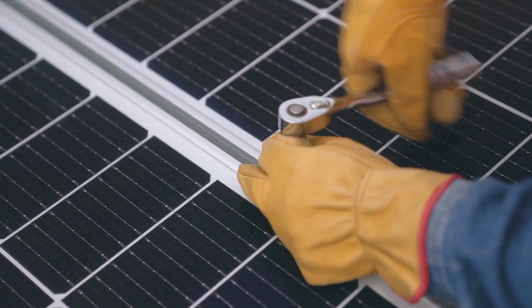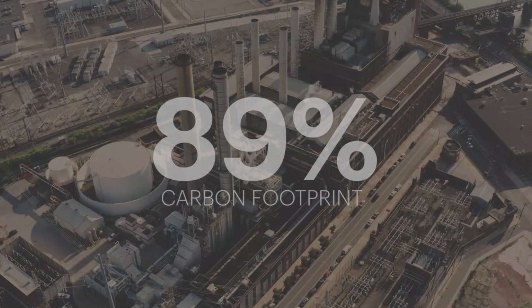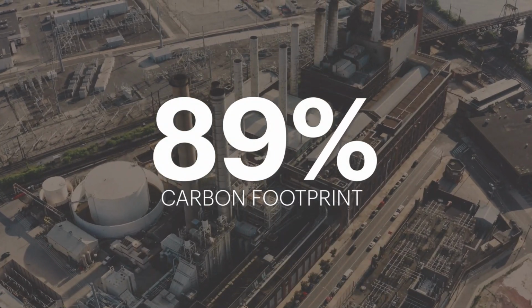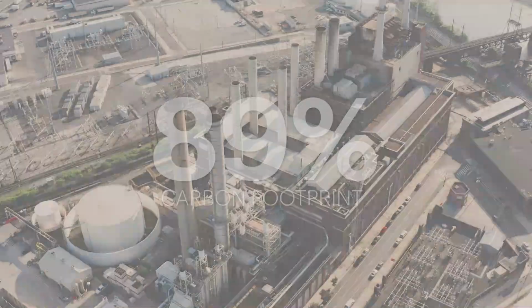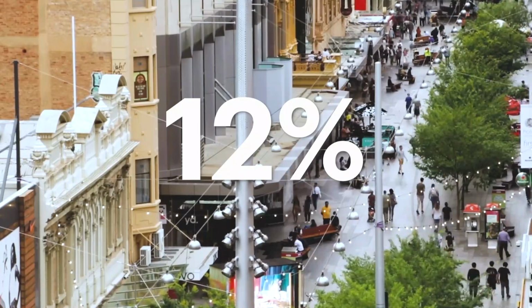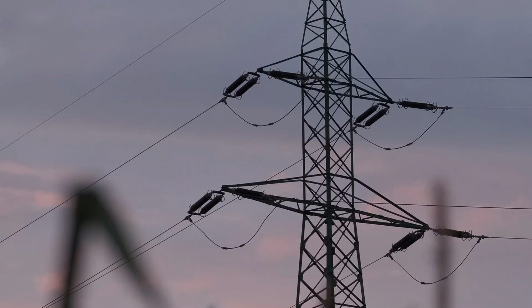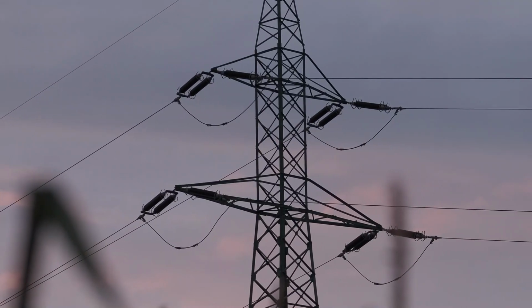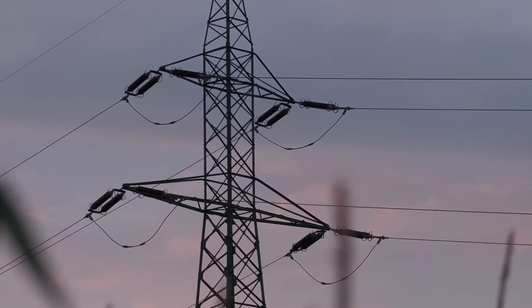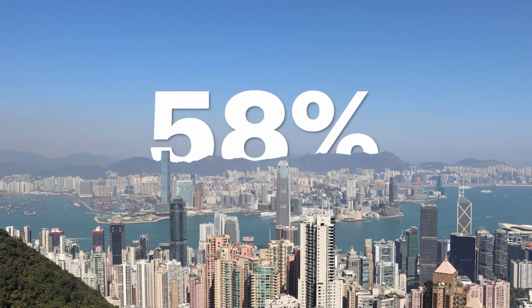Let's also look at solar PV and its life cycle, where manufacturing represents 89% of the carbon footprint if the solar panel is produced from multi-silicon, in Germany, for a 20-year lifetime and a load factor of 12%. Factors such as the electricity mix, panel location, and load factor have an impact on the carbon footprint during the production phase. As an example, a PV panel produced and operating in China has a carbon footprint 58% larger than one in the European Union.